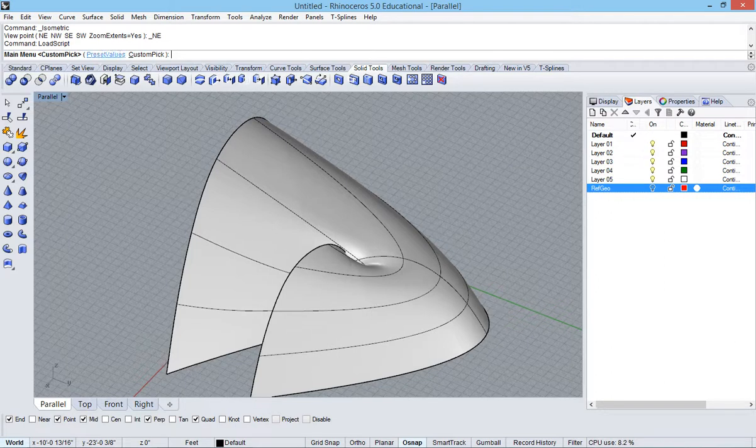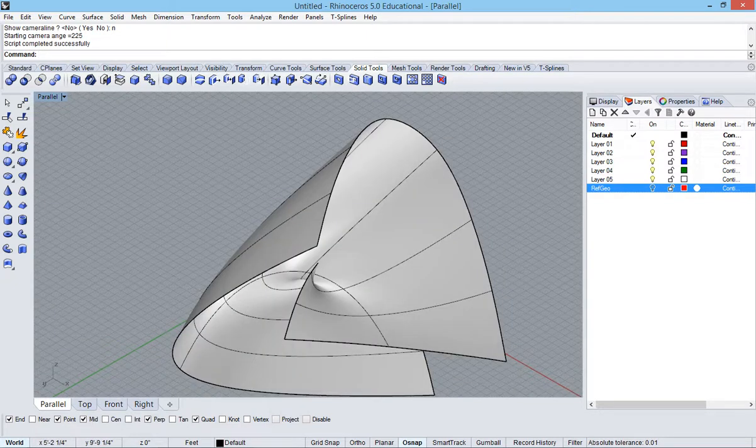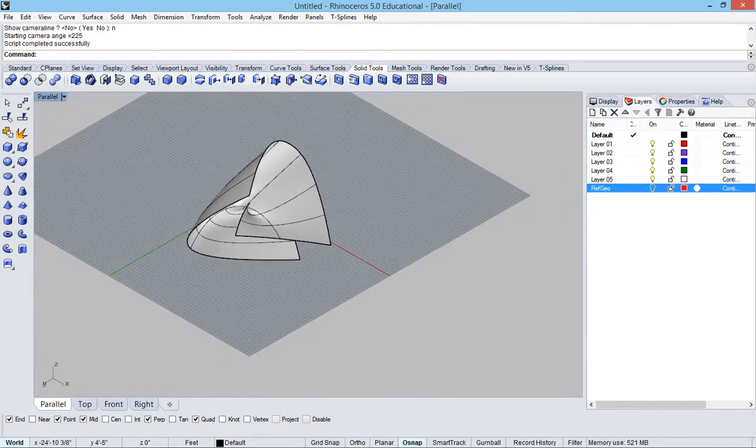Okay? So we can do preset. Let's try preset values. Let's just do X. So this is where we have to be clever. Let's do X. Let's do -30. And it won't let us do -30. So let's do 30. We might have to flip this thing upside down, which is fine. 30. Z-axis direction. So let's try negative. Does this do 0? No. Yeah, so that works. So negative on the Z gives us a worm's eye view.